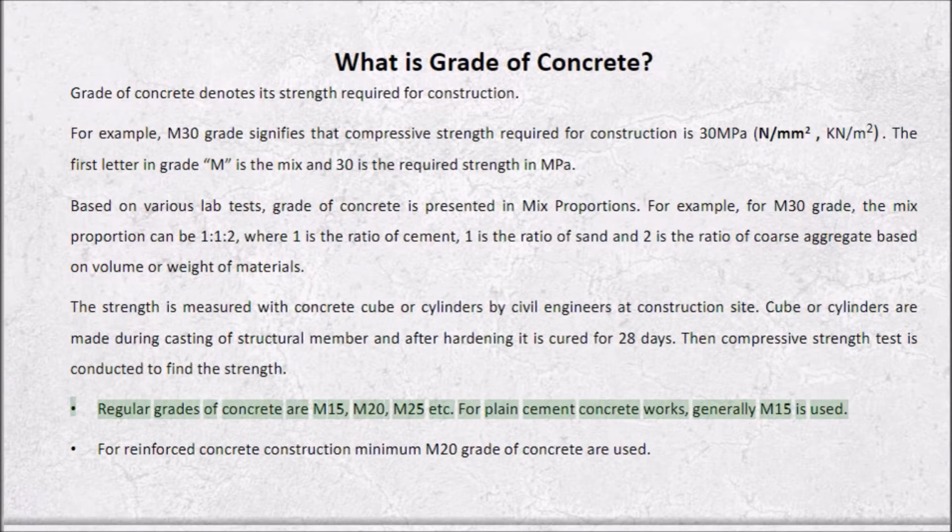Regular grades of concrete are M15, M20, M25, etc. For plain cement concrete works, generally M15 is used. For reinforced concrete construction, minimum M20 grade of concrete is used.